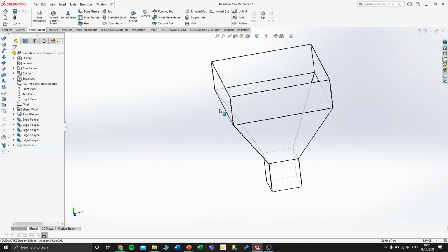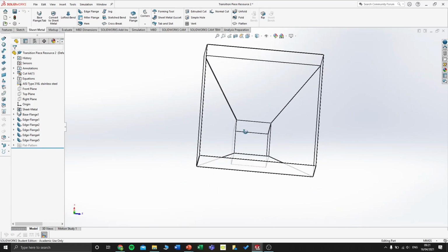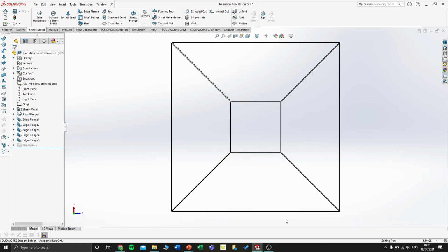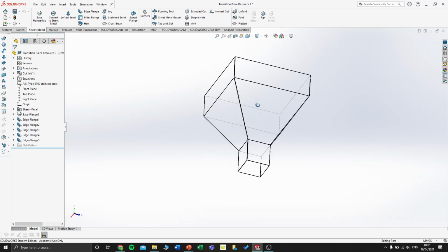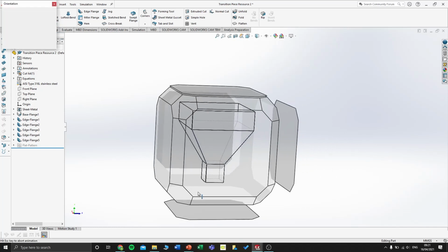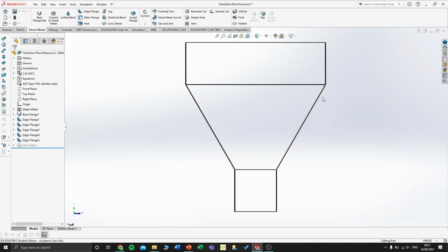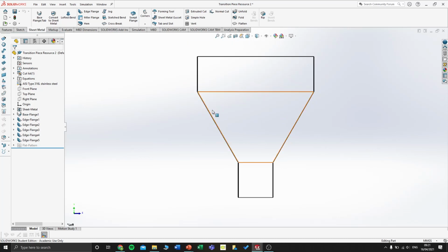If I go up to the plan of the object, I'll just rotate that the same way. This line again is horizontal, or parallel to the XY, so that means it'll be true length. Now, why I'm using the hidden lines especially is for these slanted, diagonal lines of the hopper. This is the elevation of my object. This line is at a diagonal, so it's not going to be a true length in the elevation, because it's not parallel to the XY line.